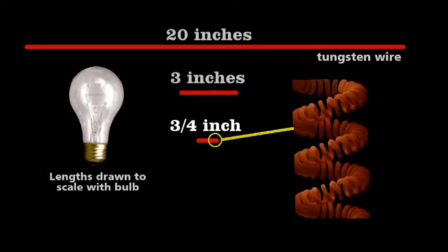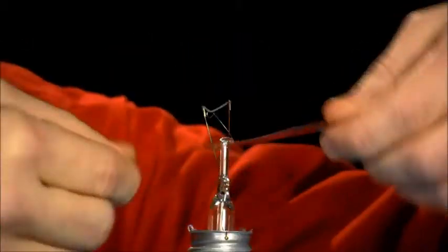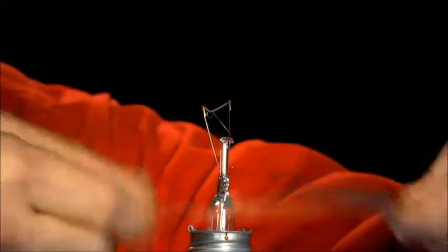Now obviously the coils enable more wire to glow, but also internal reflections within the coil can double the intensity of the light emitted. Now as an engineer, what amazes me is the ductility needed to make these coils. Let me show you what I mean by ductile. A piece of copper has high ductility. You can bend it and then return it to its original shape. Now, no way to do that with natural tungsten, it just snaps.